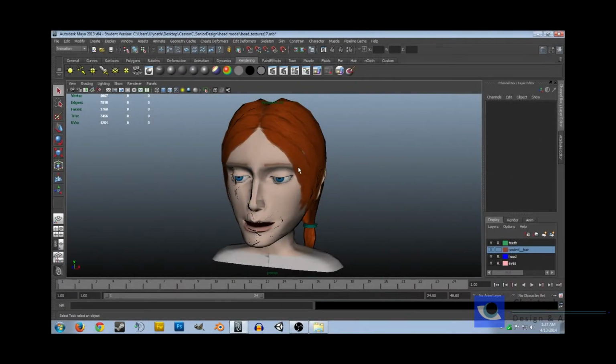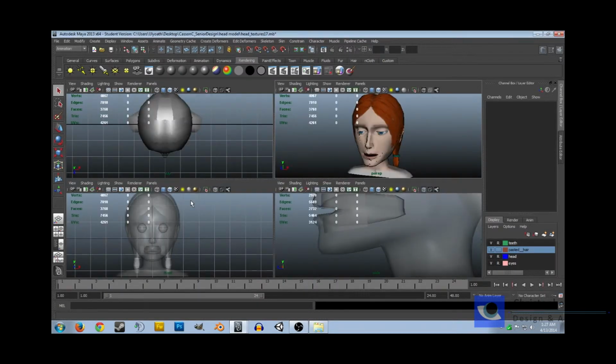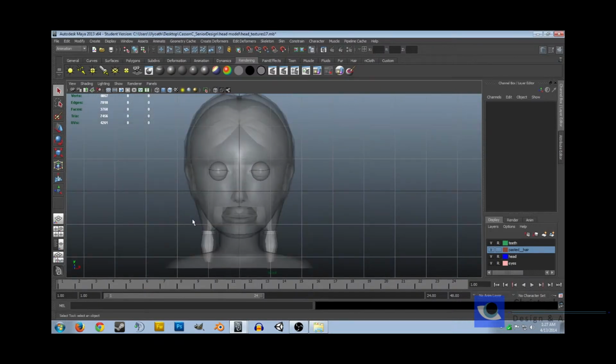So now that I have described the joint-based system and how it functions, the real fun can begin. Here we have our head model. We will start by creating the joints that will make up the spine and for the movement of the whole head. Make sure you are creating the joints in the side or top views, since you will only be able to create them on a grid and not empty space, such as the side view.